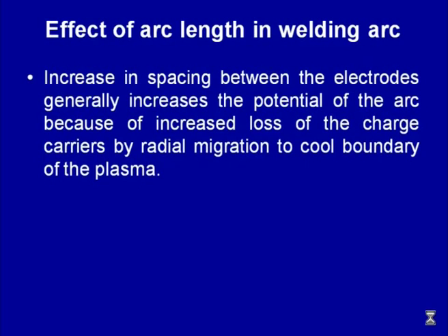So, to look in greater detail at how arc length affects the various aspects related to arc welding, an increase in arc length basically increases the potential of the arc because of the increased loss of charge carriers by radial migration to the cool surface of the plasma. So, if we see in this diagram, we have one electrode and the arc is established between the electrode and the workpiece.